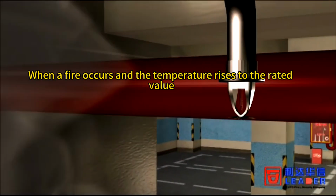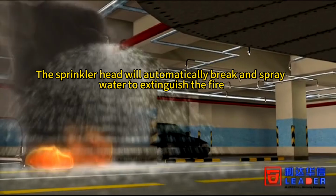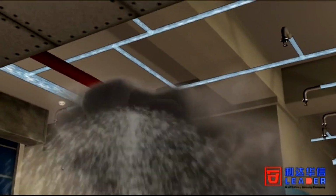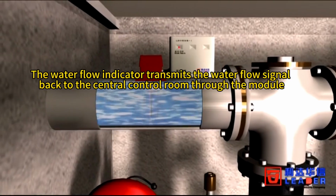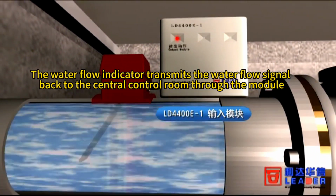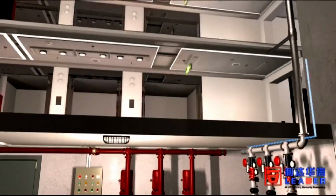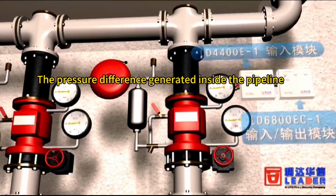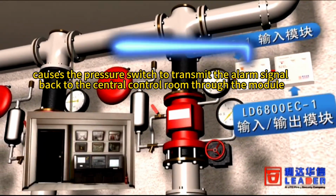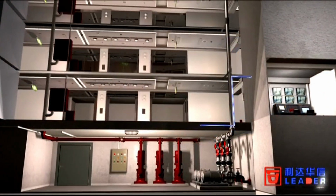When a fire occurs and the temperature rises to the rated value, the sprinkler head will automatically break and spray water to extinguish the fire. The water flow indicator transmits the water flow signal back to the central control room through the module. The pressure difference generated inside the pipeline causes the pressure switch to transmit the alarm signal back to the central control room through the module.